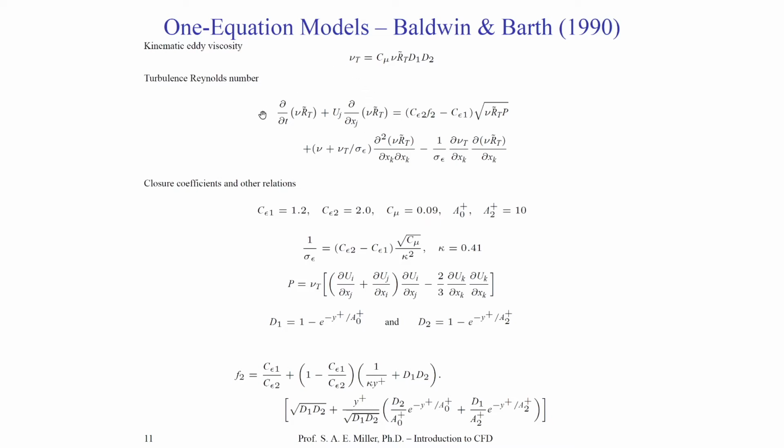The turbulent Reynolds number equation is a slight modification. It is not now tracking, of course, turbulent kinetic energy. It is now tracking turbulent Reynolds number. So you can see Baldwin and Barth have transitioned from the use of TKE tracking to the turbulent Reynolds number itself. This is a brilliant idea.